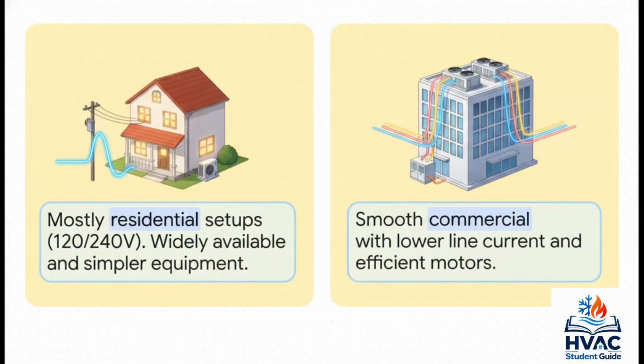This actually brings up a huge divide out in the field. You'll see single-phase power, that's your standard 120 or 240 volts, mostly in residential setups. It's simple, it's everywhere. But you absolutely have to master three-phase power for large commercial jobs. Three-phase delivers a much smoother power with a lower line current for similar loads. That means smaller conductors and way more efficient motors.